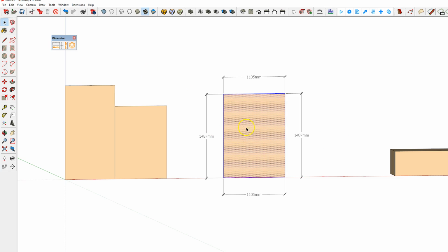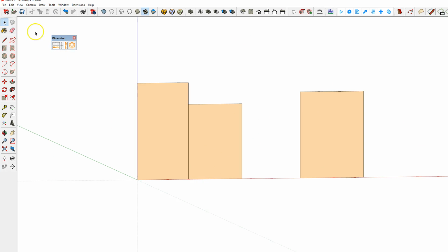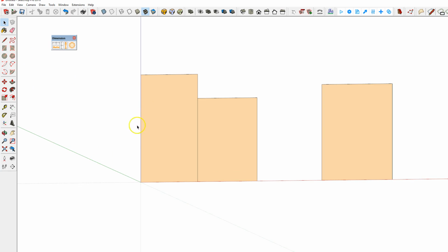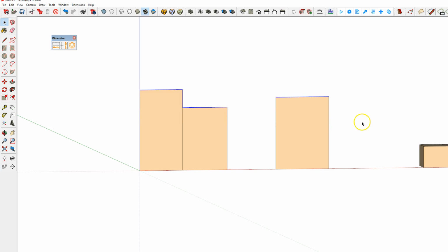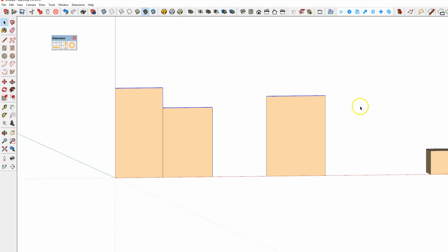So let's undo this. To remove dimensions too, you don't have to use the razor tool, you just select them and click the button again, so it's very handy. Say for example I have three lines here in a row, 1, 2, 3, but I also have a gap. If you want to add in that dimension, you switch on the gap dimension here. I will show you that in the groups when we come to do dimension in groups.